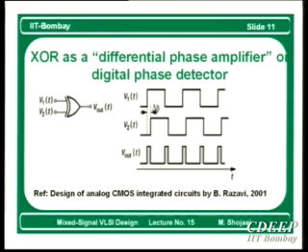What happens is these two have the same frequency, but they have some phase shift. Now, if you put it in a loop which has a high loop gain, this delta phi will go to 0. How will it go to 0? The frequency needs to change. In an open loop, this will continue forever. But now you make it feedback, and you use this signal to change the frequency.